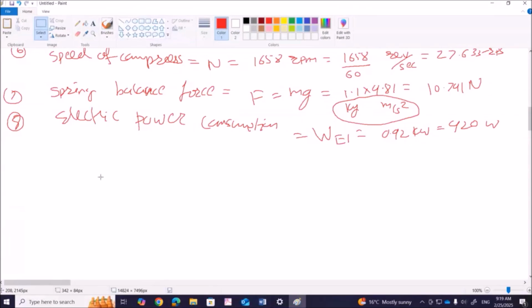So as I told you, the atmospheric air comes inside a volume flow meter. Then it goes to the pressure gauge, where it goes to the compressor, going inside, and the high pressure air will come out here. So here P ATM and T ATM. So by the characteristic gas equation, I know I can find out V ATM. So this is my first target, V ATM.